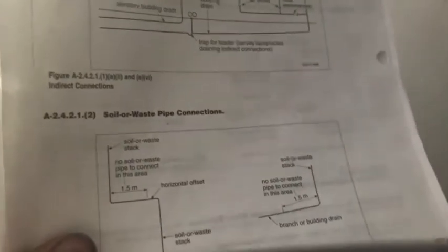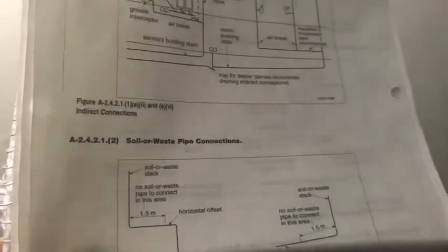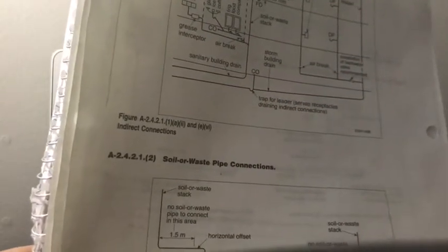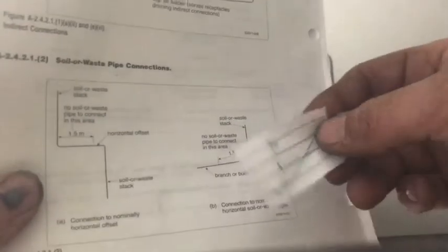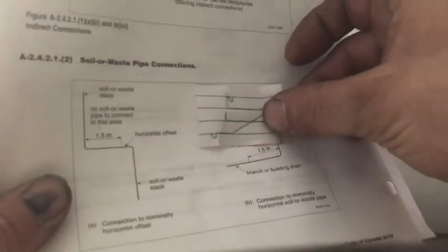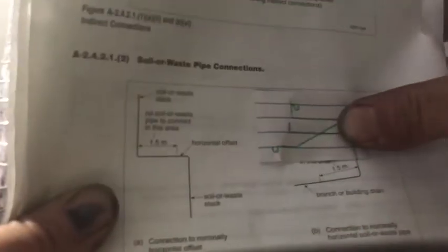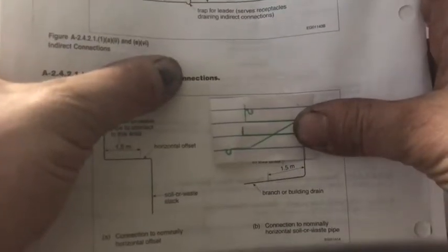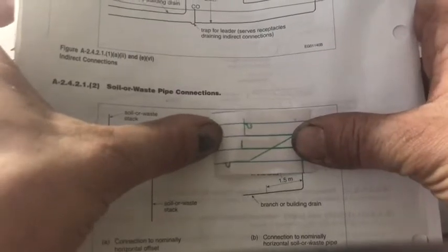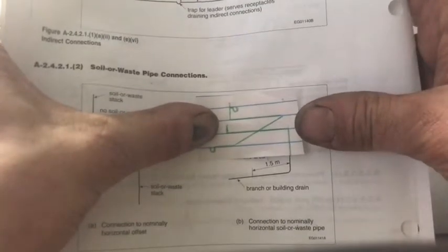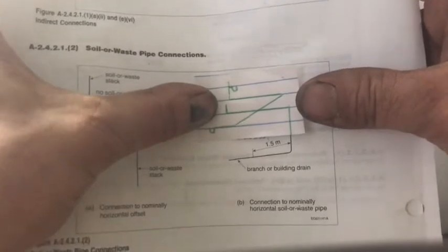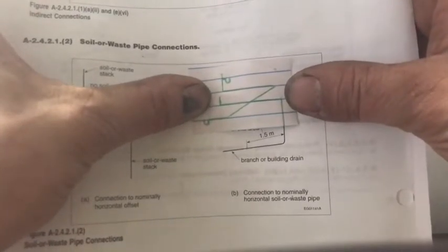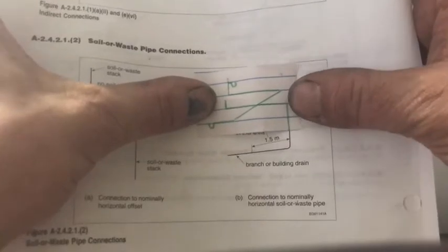Residential guys know that because it penetrates 1 story, at least 1 story. The situation where it doesn't penetrate 1 story in a residential setting, where we just have it downstairs. Because this is the first floor and this is the basement, this doesn't penetrate 1 level, it just picks up everything, and this is pretty typical bathroom group for mom and pops. This would not need 5 feet because it doesn't pick up 30 fixture units.